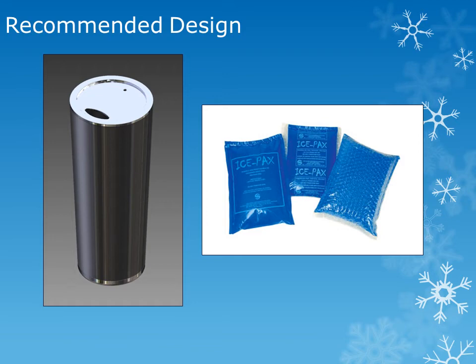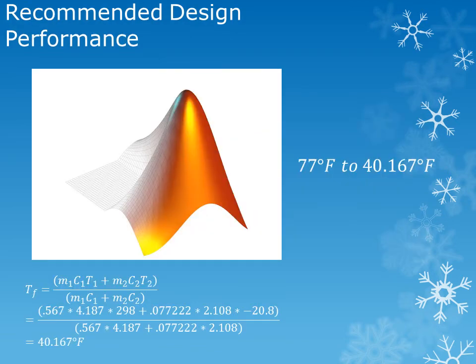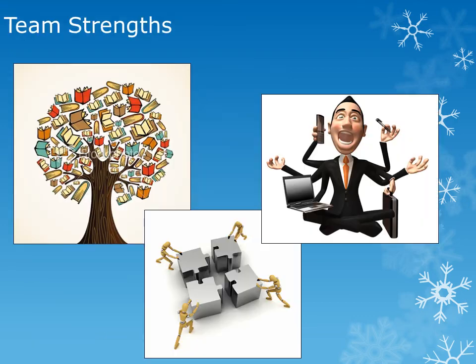As stated previously, the math model we designed could not take into account all of the improvements we did to the thermal mug. However, we did continue to run it, using the thermal compound between the walls at a below freezing temperature with a beverage of approximately 77 degrees Fahrenheit being added. The results were that it would cool the beverage down to approximately 40 degrees Fahrenheit.